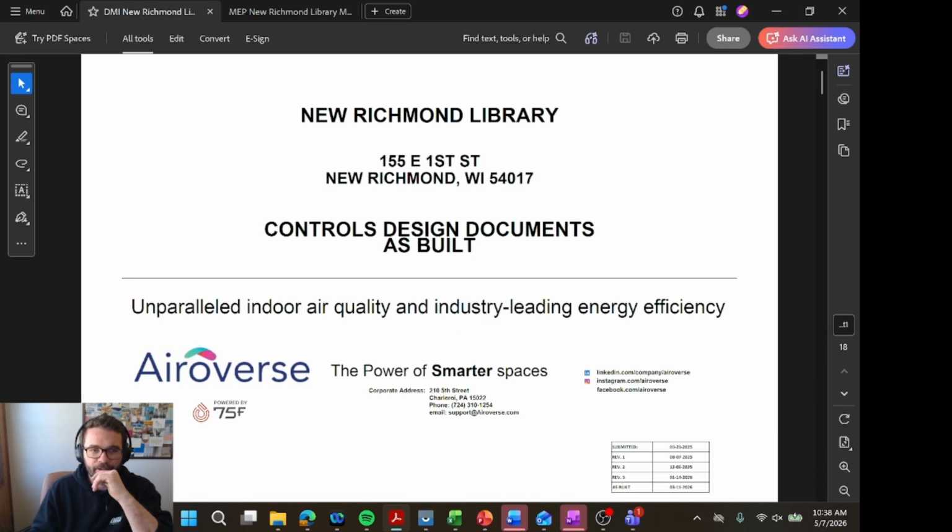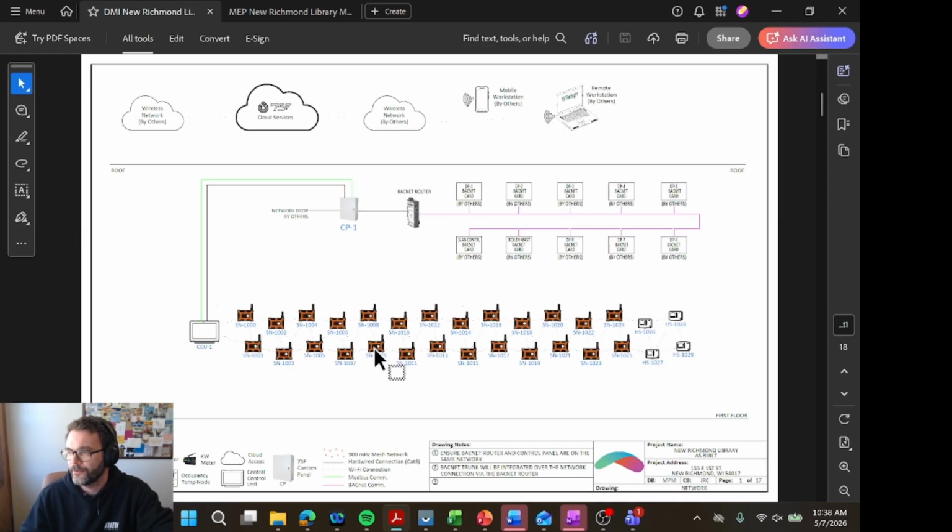And our controls design drawing, what we're really doing first, or our step 2 in this whole process, is going to be what equipment is correlated to what controls devices. So as we go through, there's kind of a recap here, but this is devices instead of equipment. So usually there's a controller for each piece of equipment or each piece of equipment that's connected.